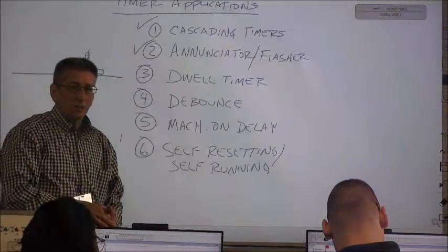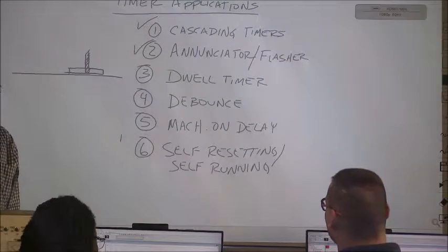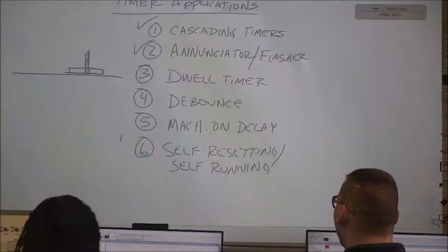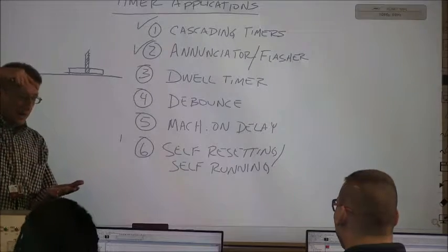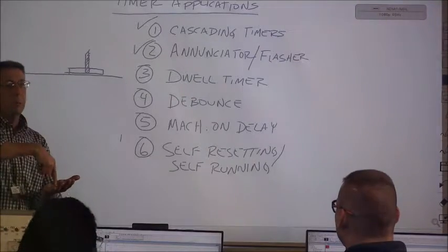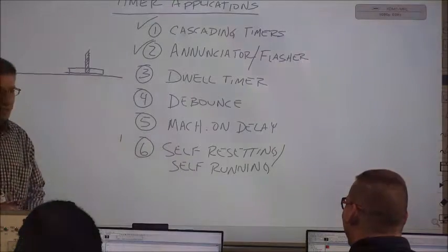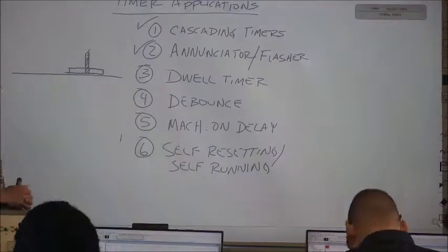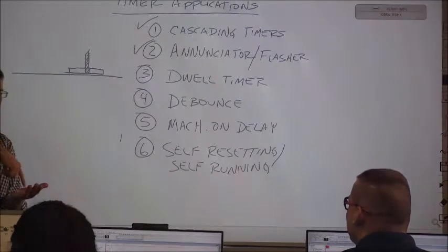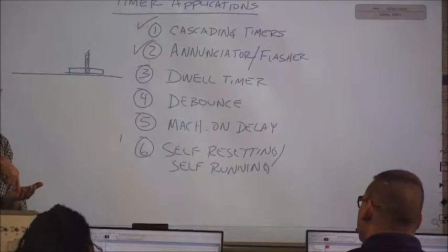If we were to just drill it really fast, what's that going to do? Too much torque, you're gonna strip the thread, break the bolt. You can do a lot of stuff, couldn't you? So what you do is you have a little bit of dwell time, you get down in the part, and you hold it there for just a second, right? You drill, and then pull the drill back out. Maybe increase coolant to cut down heat. There you go, WD-40. That's to eliminate burrs and that kind of stuff. If you add a little dwell time, it's going to help clean that hole out as it drills through the part.